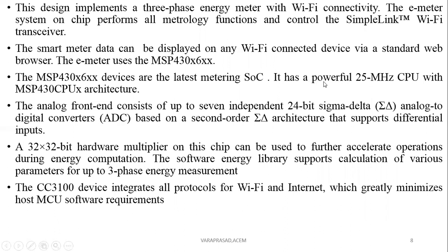Then it is operated with a 25 megahertz CPU, and it consists of 7 independent 24-bit sigma delta analog to digital converters with second order differential inputs, and also a 32-bit by 32-bit multiplier for measuring very big values. It also consists of a software energy library that supports the calculation of various parameters.